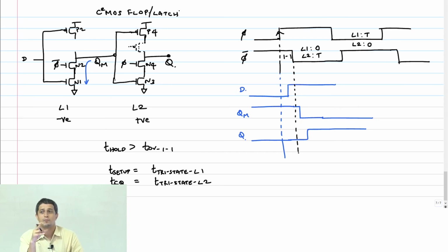It doesn't mean that both overlaps are not an issue. One overlap is still an issue, but I can alleviate that by imposing a hold time constraint. It's always the other overlap period that's a problem, and this flop is insensitive to that overlap. The non-sampling edge overlap is not an issue.